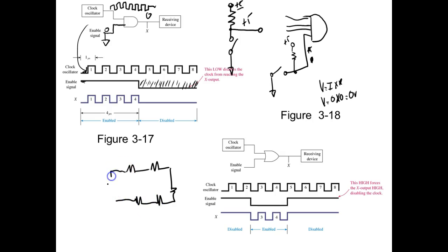So let's say I have all these resistors right here, and I open that resistor right there. How many volts is this guy right here going to drop? 0. Why? Because there's no current flow in the circuit. So that means this now has moved right there. How much is this going to drop? 0. That means this right here has moved right there. How much is this going to drop?